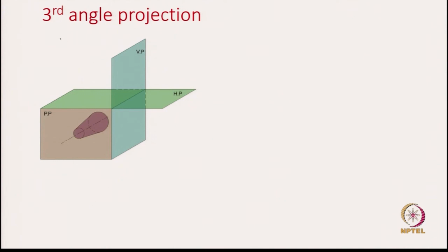So, as you can see, first we start with the third angle projection, and when we capture the front view, you remember in third angle projection the projection plane is in the middle. So, if you are trying to capture the front view, what we see is a trapezium. Okay. Now, once I am trying to capture the left side view, I look at it from this direction, and this is the profile plane on which I am capturing the left side view.